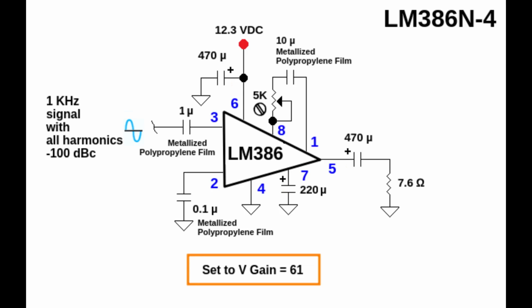The LM386 seems a nuanced device. You may change voltage gain, add additional negative feedback, and DC or AC couple the input signal. Further, you may terminate the unused input by connecting it to ground via a wire or a small capacitor, or even leave it open circuit, although leaving it open circuit is not recommended.